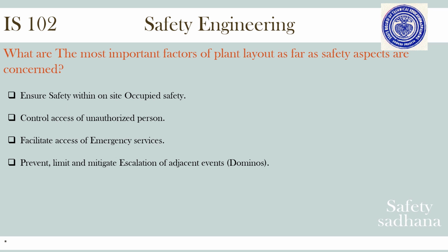What are the most important factors of plant layout as far as safety aspects are concerned? Ensure safety within on-site, occupied areas. Control access of unauthorized persons. Facilitate access of emergency services. Prevent, limit and mitigate escalation of adjacent events, domino effects.